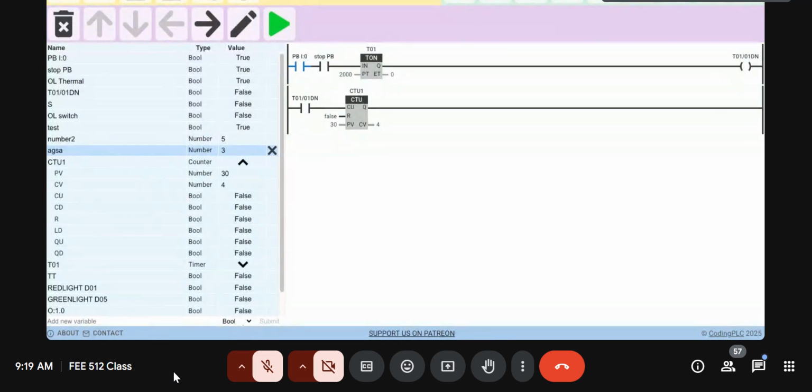And that's why you are the engineer, you need to figure out which one works and does it provide the output that you expect. If it doesn't, then what adjustments do you need to make so that it works? So sometimes the problem is not really with you or your design or your ladder diagram for that matter, but it's with the PLC that you're using. So it's usually also a very good consideration to check, what PLC do I use? What's their data sheet? What are some of their instruction sets? And then how do we achieve my objective using this PLC?